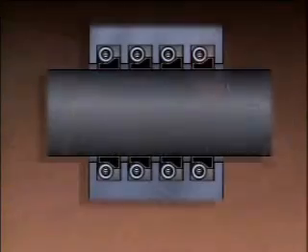We've seen how the gland steam seal system and gland steam seal exhaust system work. We've also reviewed some common checks that are made on these systems. The points where the shaft passes through the turbine casing must be sealed to prevent steam from leaking out of the turbine and air from leaking in. Several types of seals are used to prevent these conditions from occurring. Probably the most common seals are steam seals, but two common alternatives are carbon seals and water seals.